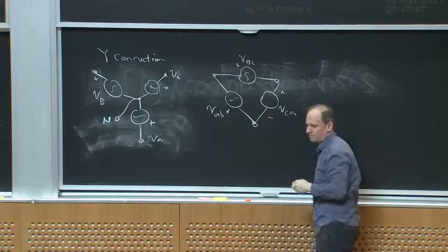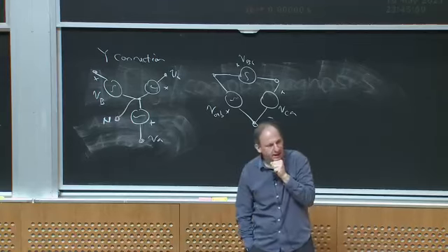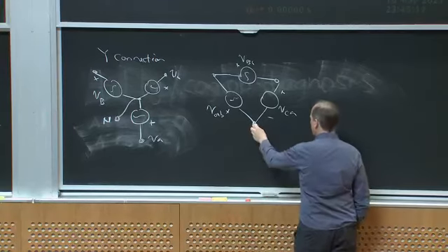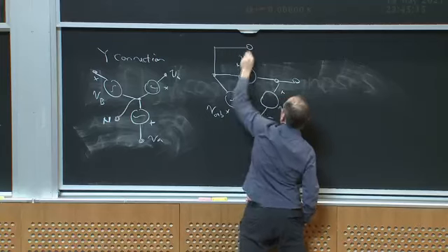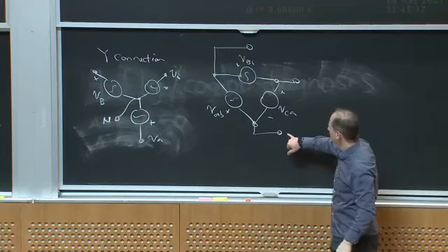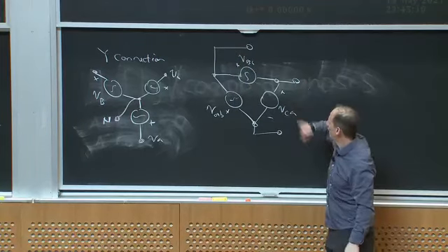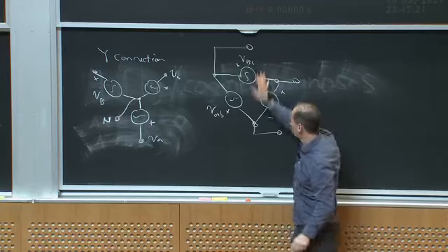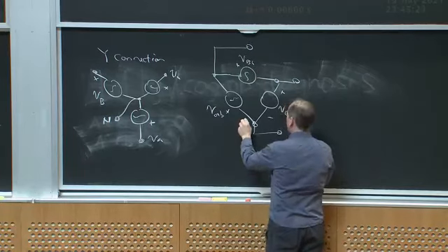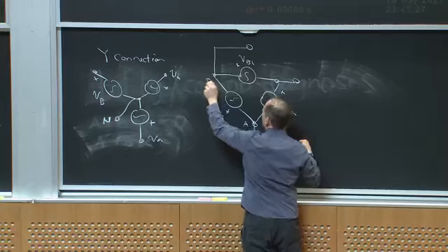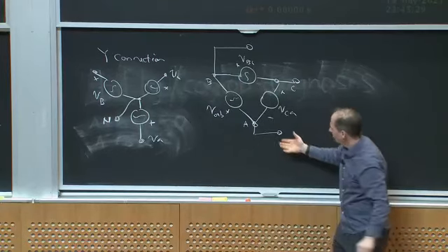And if I did that, then I could bring out these 3 leads. Now I have no neutral, but I still have A, B, and C, and I can just do the differential connections. So this is node A, this is still node B, and this is still node C.